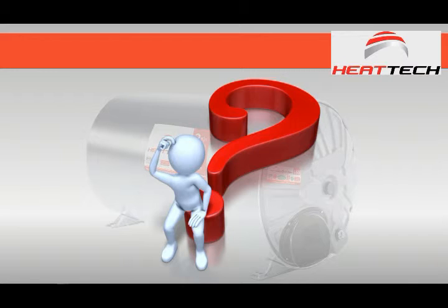You make space. If you read the standard, it says that you can cut directly in the line, provided you are 700 millimeters away from the outlet. So you can run it level with the top of the geyser as long as it's got 700 millimeters. That is okay. That is correct. Thank you, Lee. And if you speak to one of the manufacturers who have a very light vacuum breaker jumper, they'll tell you a different story. So I want you guys to go and find out who that manufacturer is.